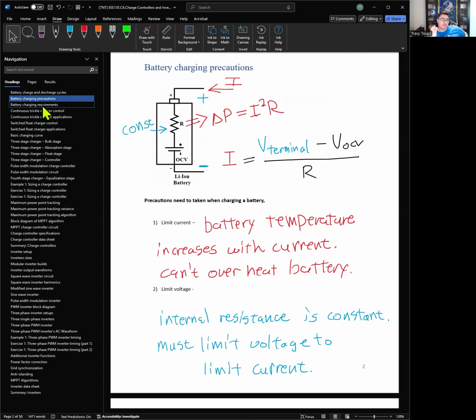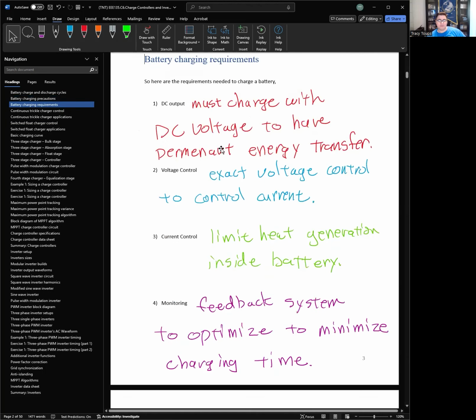It might say, the limit of this charging battery is 100 amps at an ambient temperature of 80 degrees Fahrenheit, right? So as long as you're at 80 degrees Fahrenheit, you could charge consistently at 100 amps. If you try to put 200 amps in, you're going to overheat it, and if you do it too long, you're going to break it. Okay, so that's how you read this.